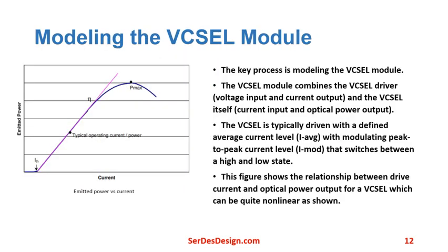So, modeling the VCSEL module. The key process in modeling the EOE retimer is to model the VCSEL module. The VCSEL module combines the VCSEL driver, which takes a voltage input and provides a current output, and the VCSEL itself, which takes the current input and outputs the optical output power.